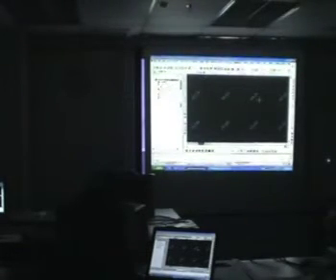A very common problem here in Malaysia is that most consultants receive drawings from the surveyors in this format, where you only get a 2D format. It's just a drawing. Maybe you've got points or just text, but you don't actually have points in your 3D positions. The Z values are not there. So that becomes a problem because most software in the market now, you need to have the 3D value before you can run any functions.